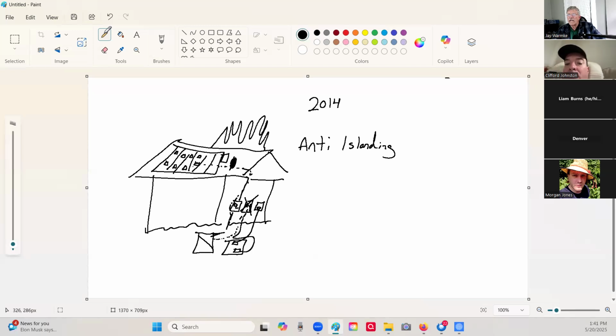Every single panel is going to get its own little inverter. So we can put the MPPT on it so that every panel now operates independently. We can put the anti-islanding on it. So as soon as it loses sight of the grid, it shuts off at the panel. And how about if we also put communication so that I can monitor every single panel, and if one has a problem, I know which one it is, right? Why not put a little communication device in there?